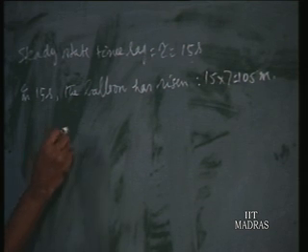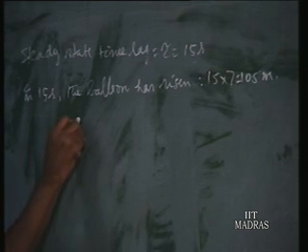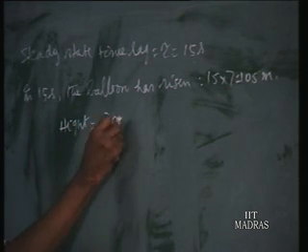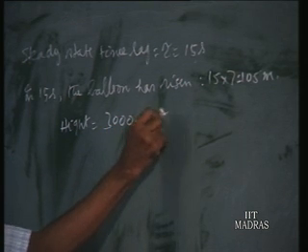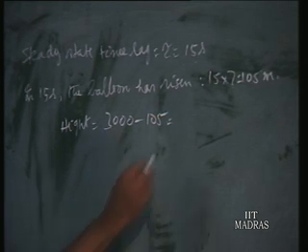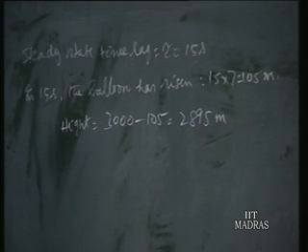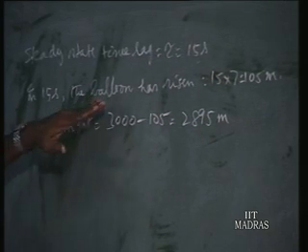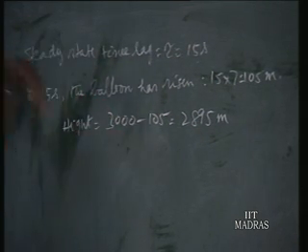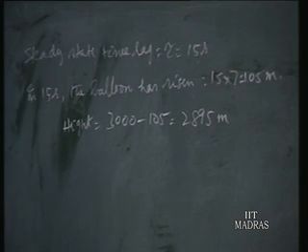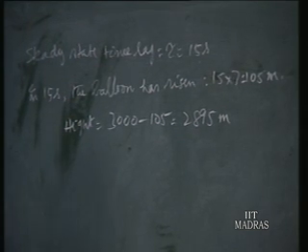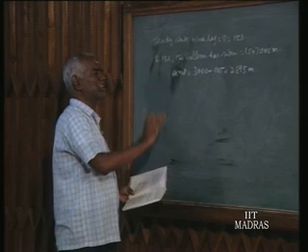So the height is equal to 3000 minus 105, which is 2895. When it was at this height, the temperature was minus 1 degree centigrade, but it was shown 15 seconds later, as per the theory we found earlier. So this is the actual height. But at 3000 meter, what should be the temperature? That is the steady state error.